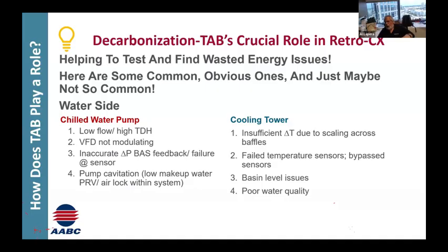The way you would know that is if your pump is sitting there rocking along with the cavitation. Everybody here understands it on a fan curve, that you don't operate a fan to the left of the curve, in the unstable range. Operating below the curve on a pump is the same thing. I just wanted to point that out to everybody.